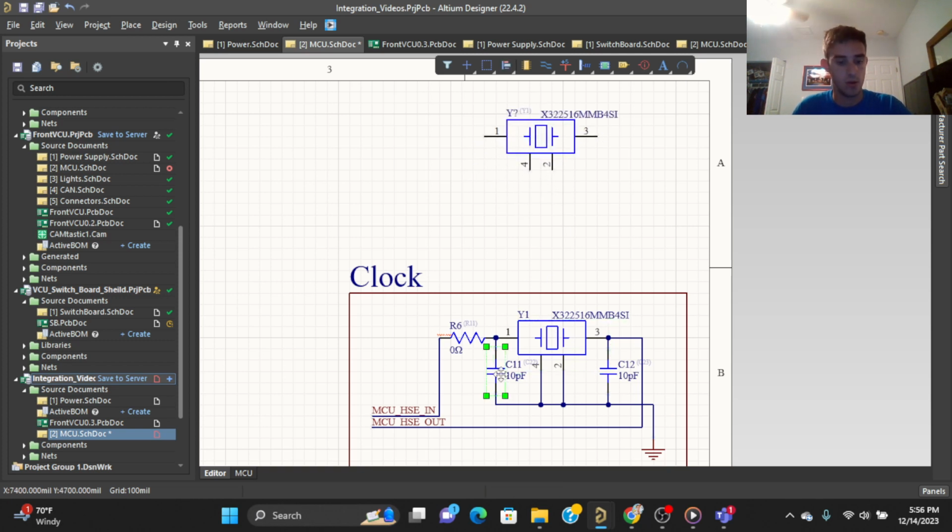Right now, our 2 capacitors I'm going to place right beside it and below it, and I'm going to connect the capacitors up to terminals 1 and 3. And I'm going to move them up a little bit. Okay. And now I'm going to connect the other lead of the capacitor up to pins 2, 4 into the other capacitor, and that will go straight to ground.